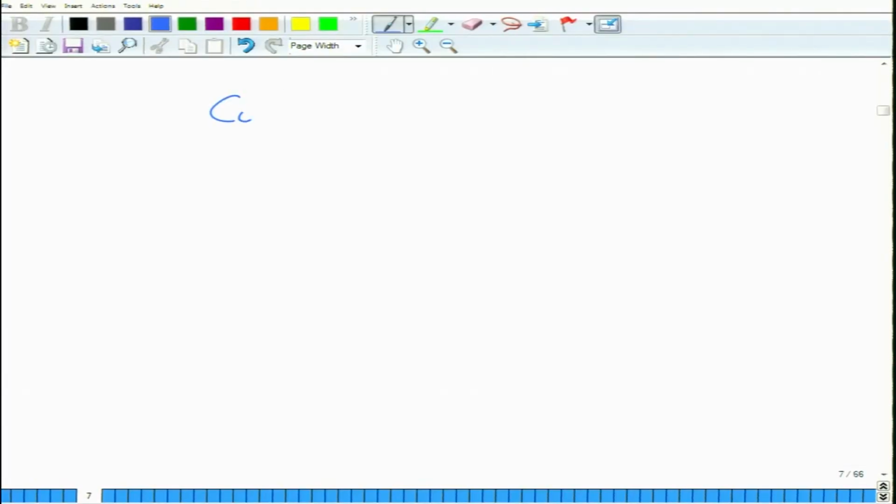So you have to choose a radiation for iron containing materials whose wavelength is higher than the wavelength of iron. So for these we choose, for example, cobalt K alpha. Cobalt K alpha has a lambda which is 1.789 angstrom.